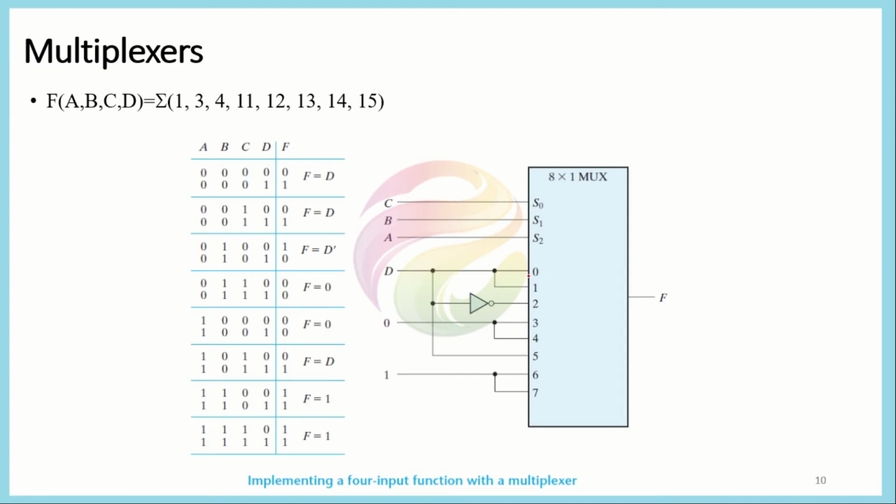Now we will see how this whole system works, because we have three inputs, or a 3-bit selection line, for the 8 cross 1 mux, and depending upon the values of these, we could have two different values of D. Either it could be 0 or it could be 1.